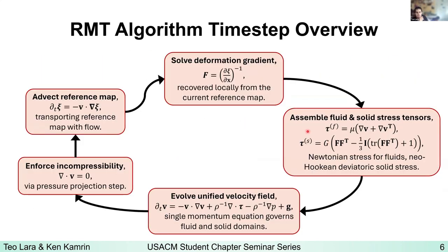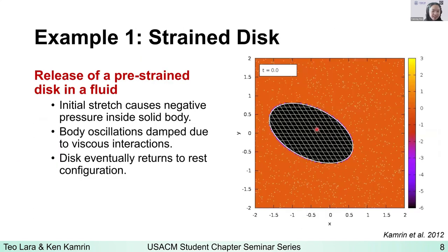So you can just imagine doing that with a different relationship, right? All you need is this deformation gradient. So you could model a viscoelastic solid or a plastic solid, or some solid with material dependent properties like I mentioned previously. So in principle, yes. I'm sure there are complications that may arise, but because you have this nice separation of the deformation gradient from the stress tensor, you should be able to do whatever solid properties you're interested in doing.